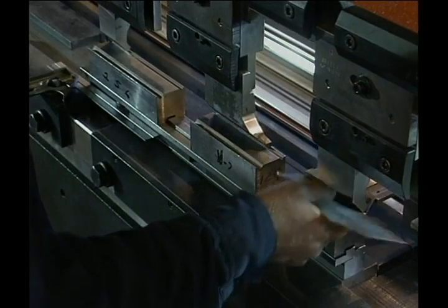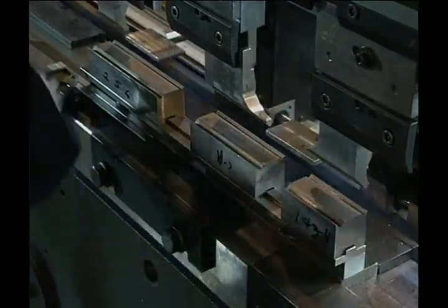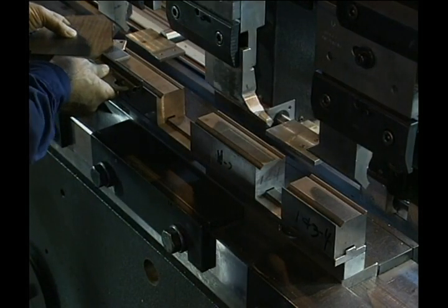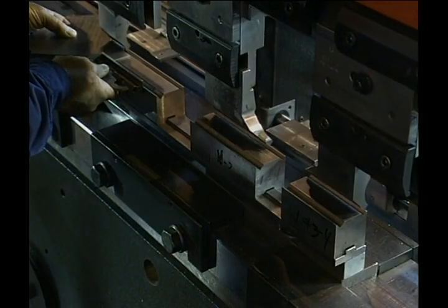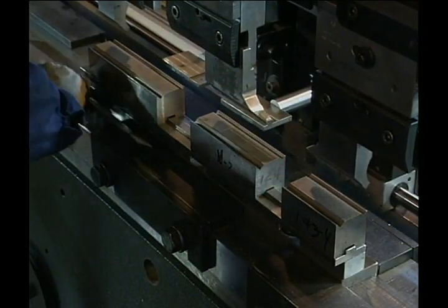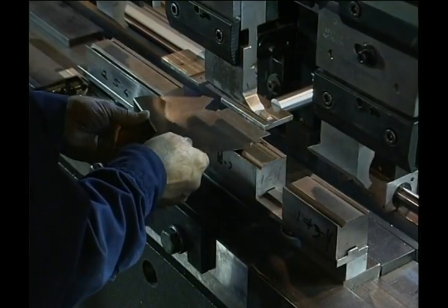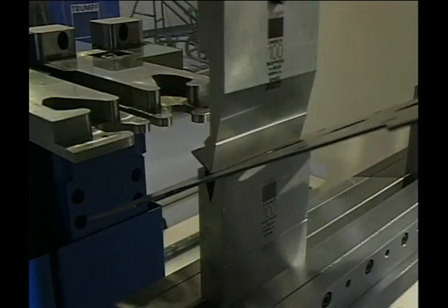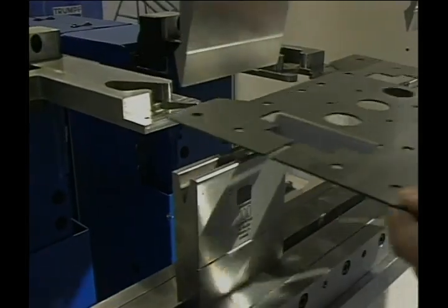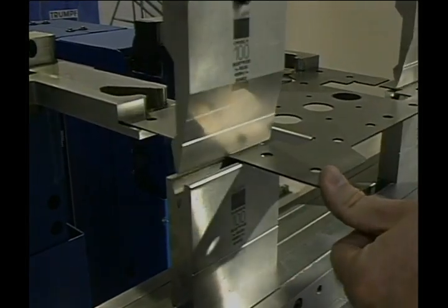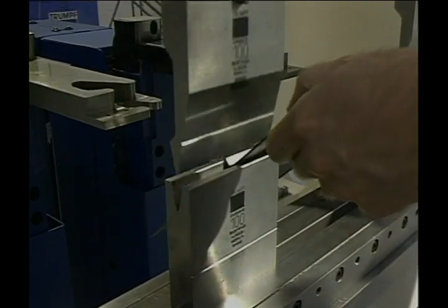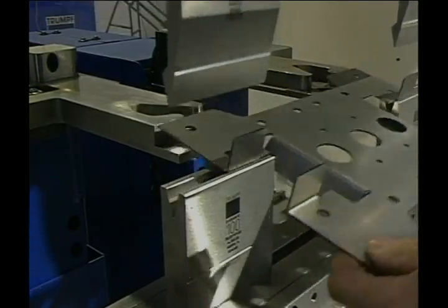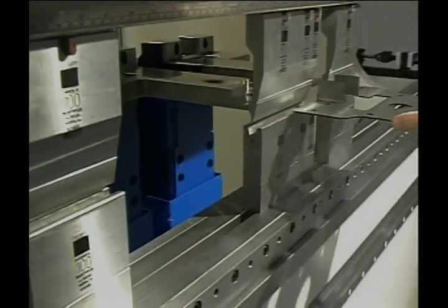The position of the workpiece and the stroke of the punch are critical variables in the bending process. Computer-controlled gauges have improved press brake accuracy and made possible the economical production of multiple bend, multiple stroke parts in a single setup. These programmable CNC-controlled back gauges are servo-driven and change their position automatically for multiple bends required on individual parts. CNC gauging is also used to control the depth to which the punch penetrates the lower die.